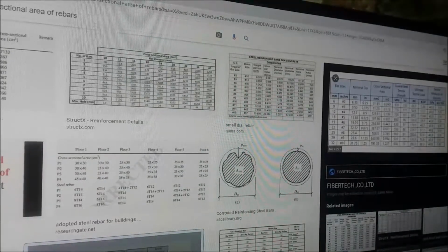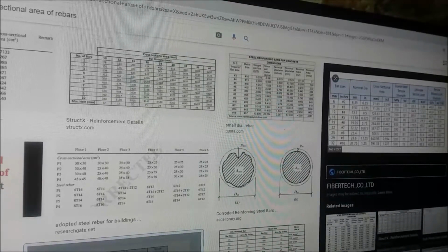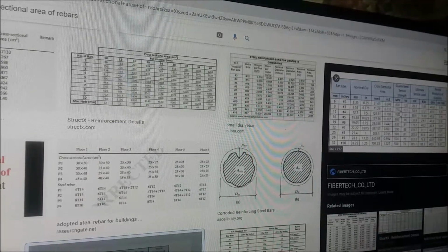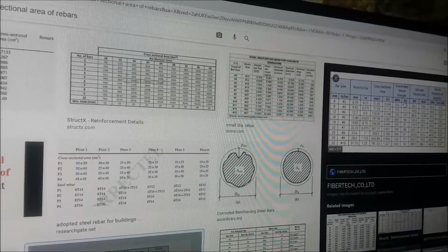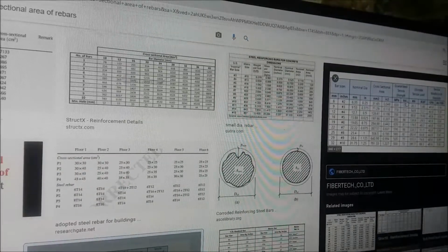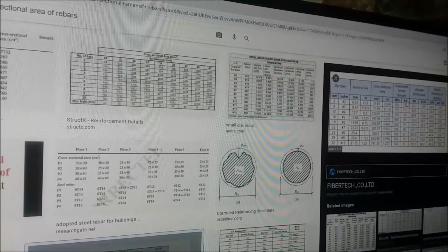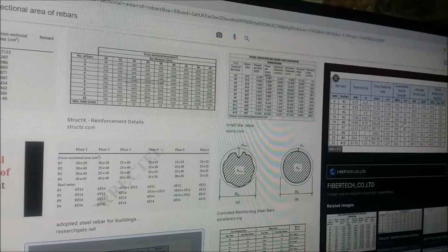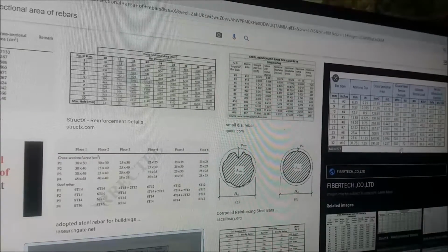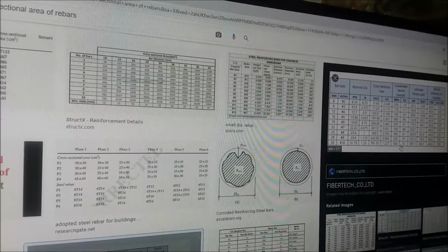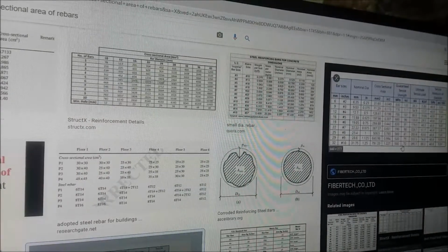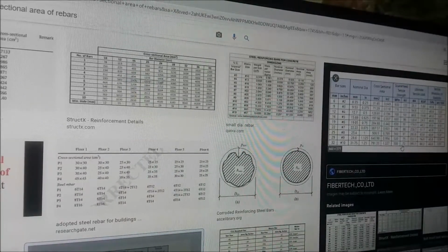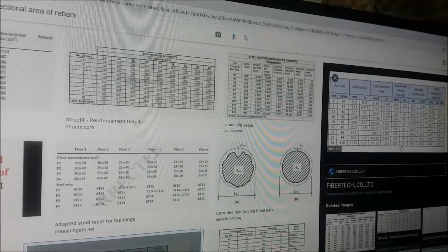You're looking for cross-sectional area of a particular size of bar and how strong it is. And you want it in square inches. So it says K, that's thousands, SI square inches. So this 101 is 101,000, and this is 96,000. And you'll notice that as the bars get bigger, the allowable stresses go down per square inch, but they're going up drastically on the square inch side, so the actual strength is going way up.